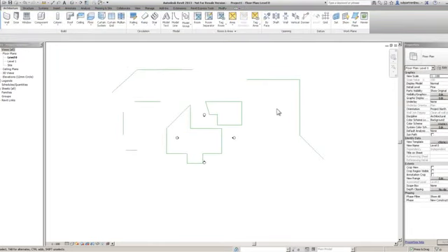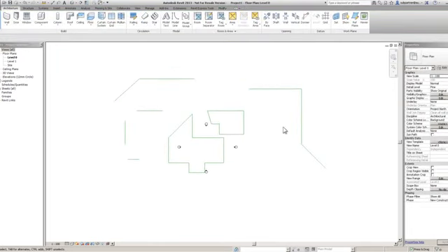Now, I'm just going to zoom out a touch. Another one: windows. In AutoCAD, we always use windows for selecting things, and it's very, very similar in this. If we move our mouse over to the left, and this time, instead of left clicking, we left click and hold, and just start to move my mouse down to the right. I'm going to move it slowly. It works exactly the same as AutoCAD. Can you see, just there?